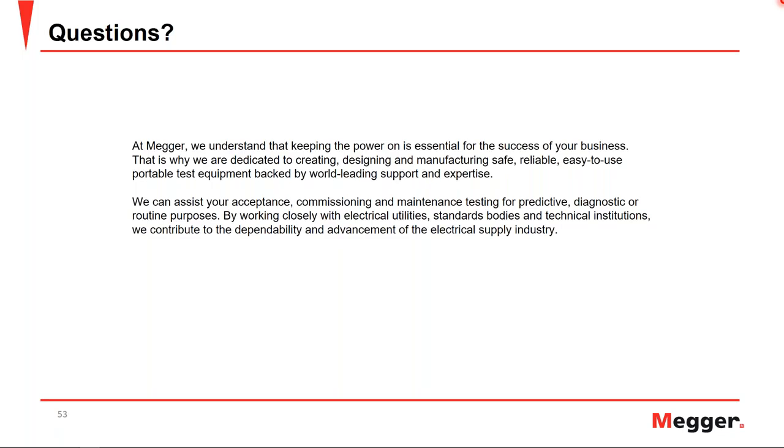So the ground cable must be placed on the test specimen ground, and all the grounds must be common. It is important to remember that the ground for the control unit must be the same as the ground of the high voltage unit, and then attached to the ground or the chassis of the transformer as well, or the test specimen. Otherwise, the LED that indicates the open ground will be illuminated, and only once you have a common ground will that light turn off and allow you to perform the test.